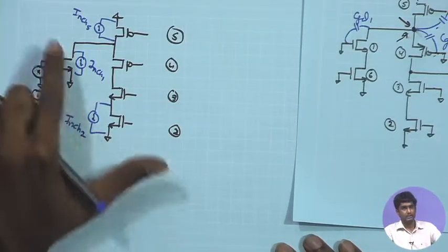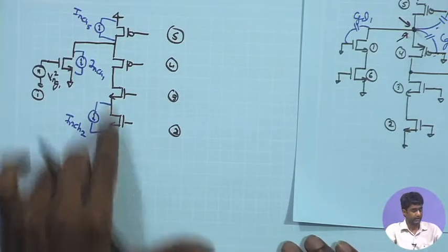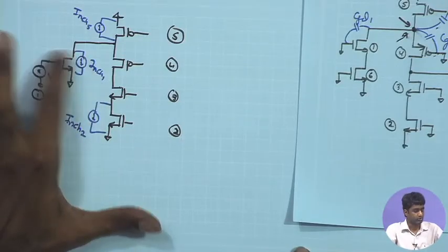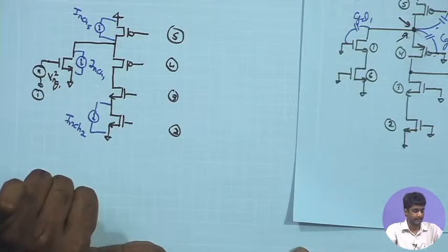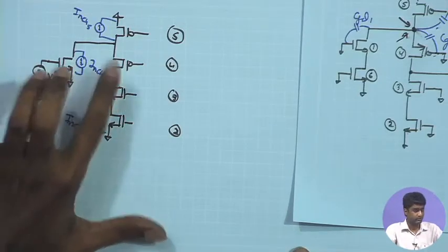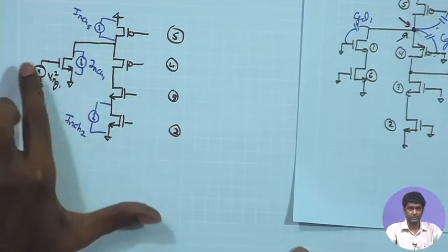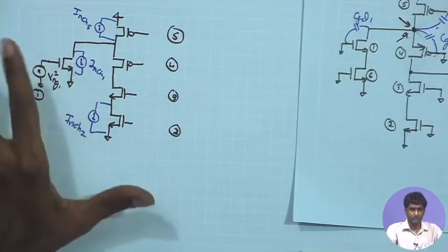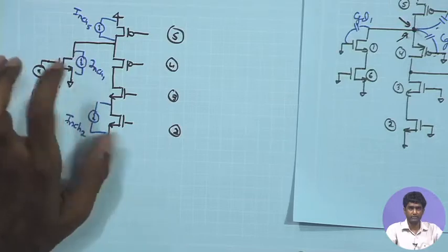These are the thermal noise currents associated with the channel current for the 3 MOSFETs, and their sources are at ground, and therefore I can also convert this channel current into an equivalent voltage at the gate, and the conversion is simple. You just need to divide this channel current value by gm squared, because the equivalent noise voltage V_NG squared times gm squared will result in this equivalent channel current. So, I have 2 sources.